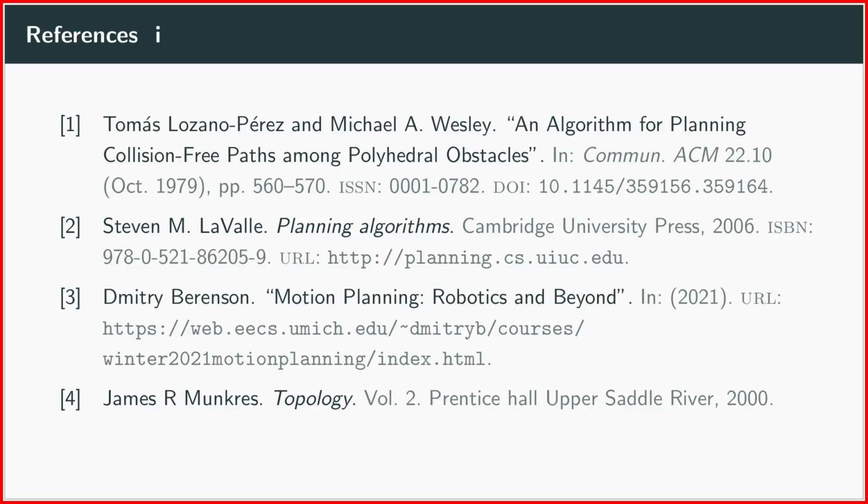And then another question: if you wanted to energetically optimize your joint motions, if you want to reduce energy consumption for joint motions, could that be implemented as a metric, or where would you separate this? Yeah, so this would basically be something which we call an optimization objective, where we want to prioritize different paths. So for example, in that case, you don't want the shortest path, but you want the energy-minimized path. That would be a topic for optimal motion planning, and this will come in a later lecture.